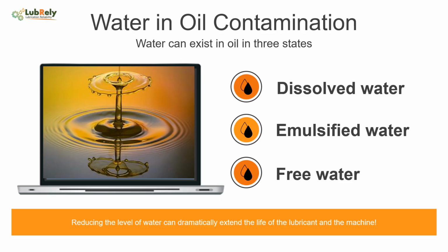When sufficient water exists, or when the oil has adequate demulsibility, free water will collect. Because water is typically heavier than oil, it settles below the oil, at the bottom of sumps and reservoirs. Because the effects of free and emulsified water are more harmful compared to dissolved water, a general rule of thumb is to ensure that moisture levels remain well below the saturation point. For most in-service oils, this means 100 to 300 parts per million, or less, depending on the